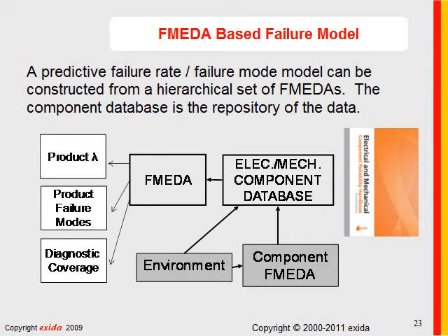If it's a complex component, like a microprocessor, you typically do an FMEA on the component, hopefully in conjunction with one of the component manufacturers. And I can tell you that at Exeter, people like Freescale and Texas Instruments and Analog Devices actively participate in this kind of analysis. And we use the environmental variables in the component analysis, or FMEA, to determine the component database.